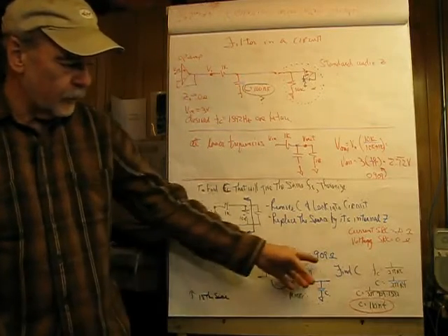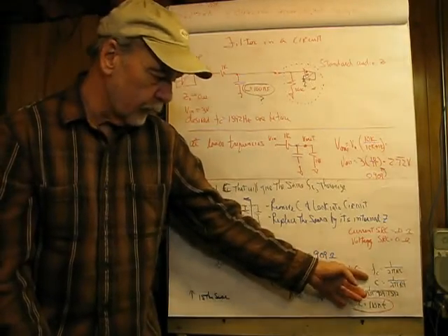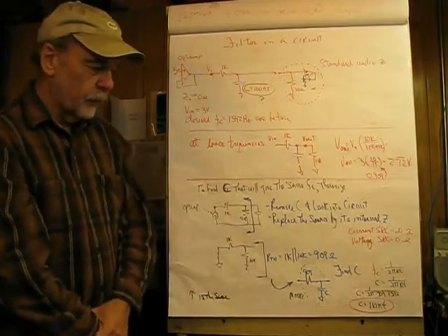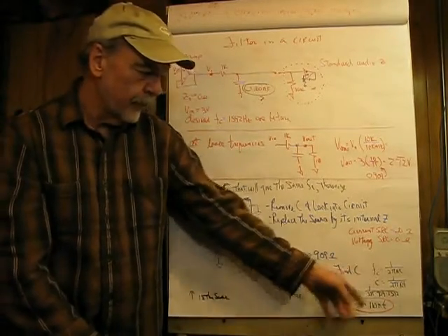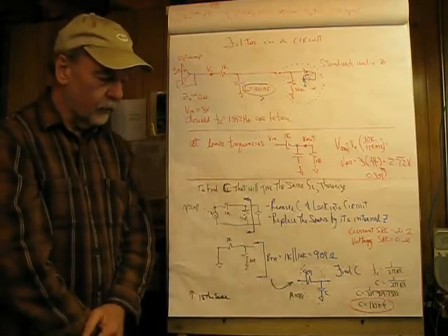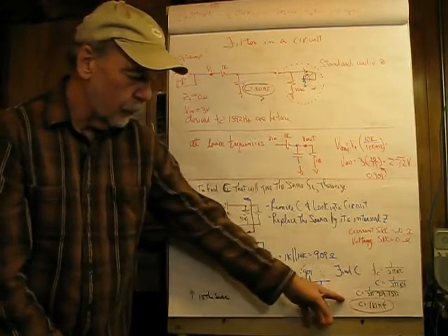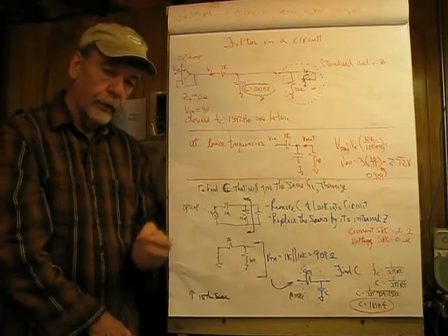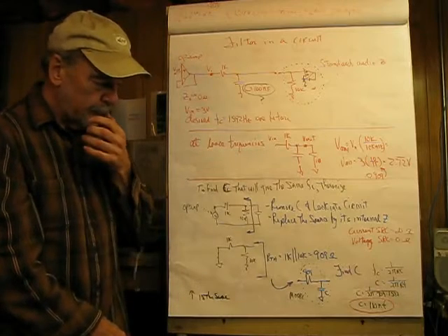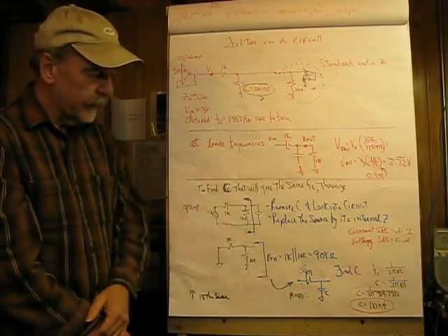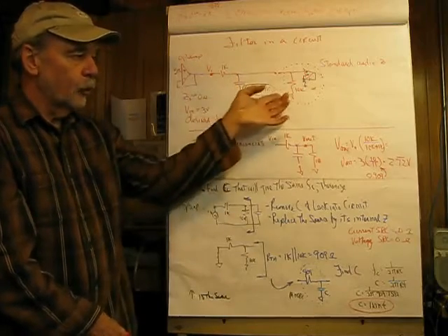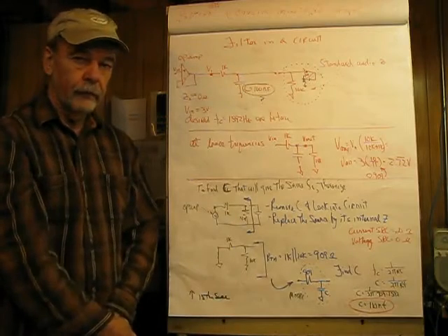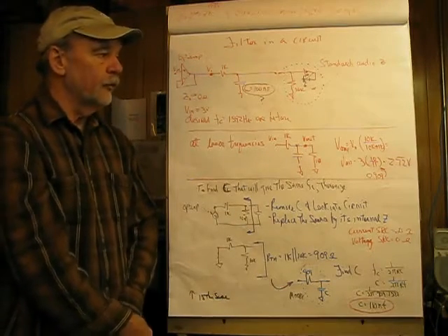So to find C here, all we have to do is take a look at our equation for finding the critical frequency, 1 over 2 pi RC, and then wiggle that around a bit to find out what C is, and that comes out to be 110 nanofarads, which is a little bit higher than the unloaded value of 100 nanofarads that we predicted. So this is a fairly straightforward calculation, and it's based on real-world values here, because typically you're not going to have this being fed into some infinite ohm thing unless it truly is an op-amp.